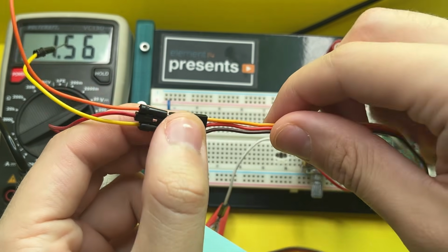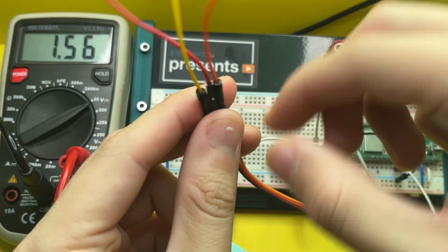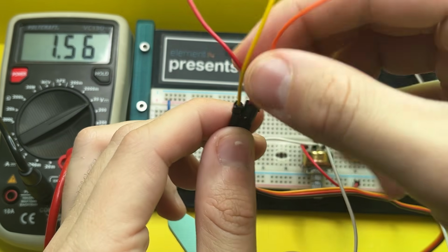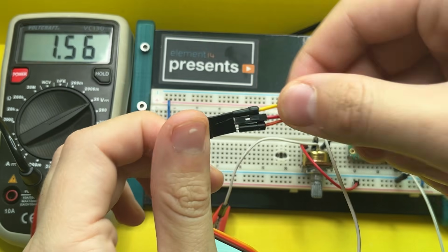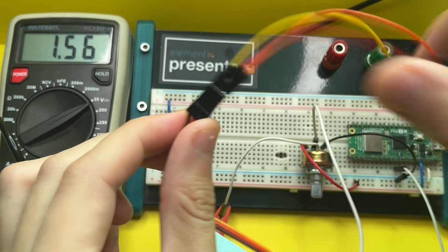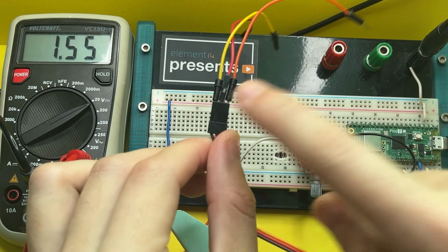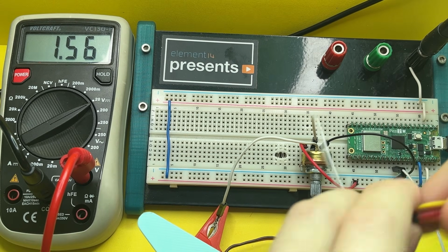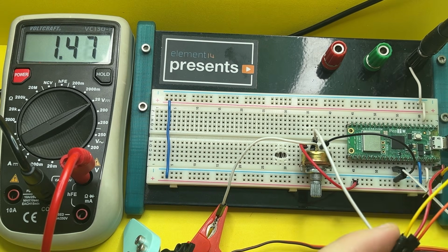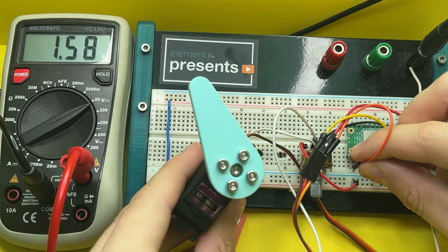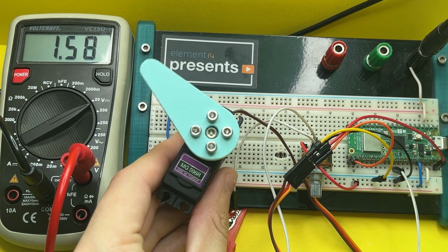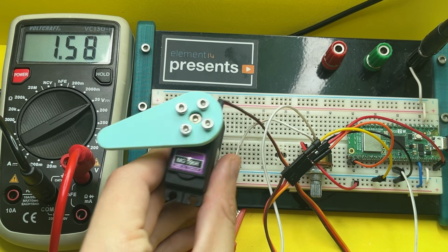So that signal wire, we're just sending it a PWM signal of a certain duty cycle. We will discuss that in the 4th video in more detail, but all you need to know is that this microcontroller will send a signal through a single wire, and it will set an angle for this. So let's connect it right up. And now if we connect this wire here, you will see the actuator moving.